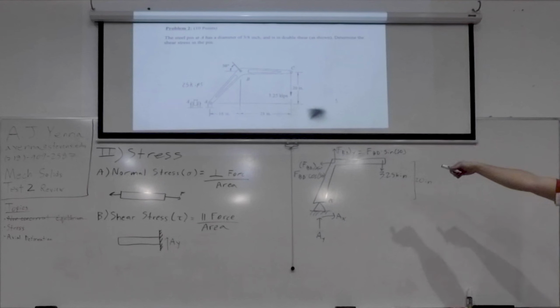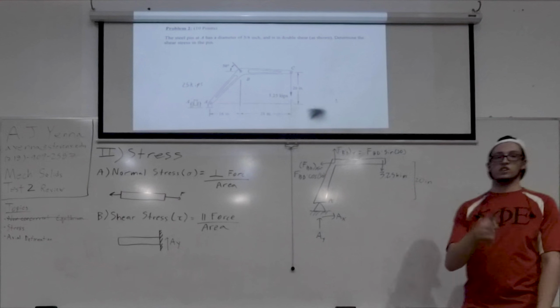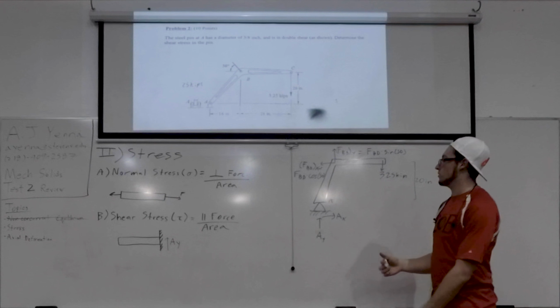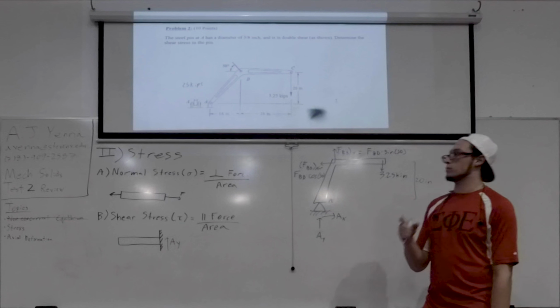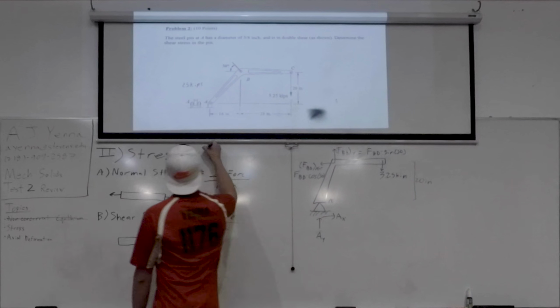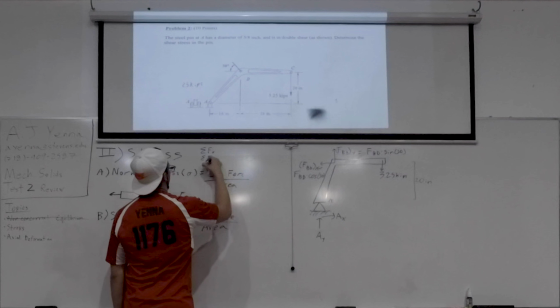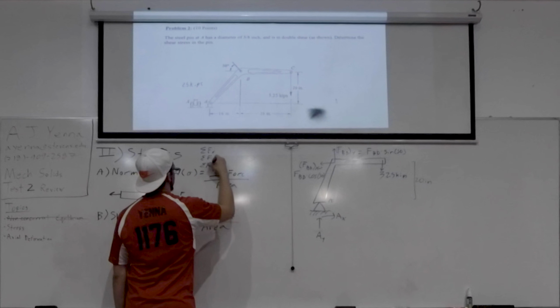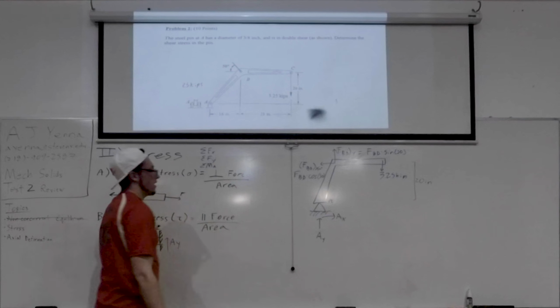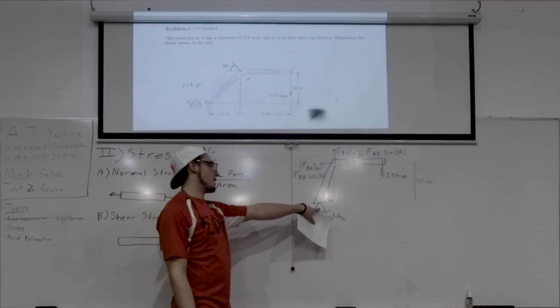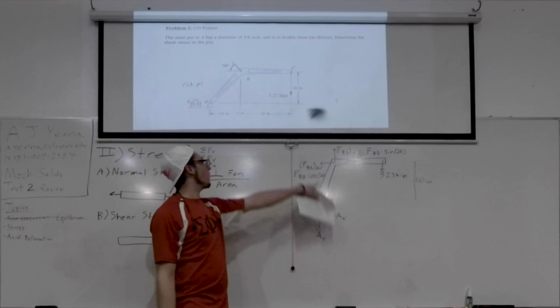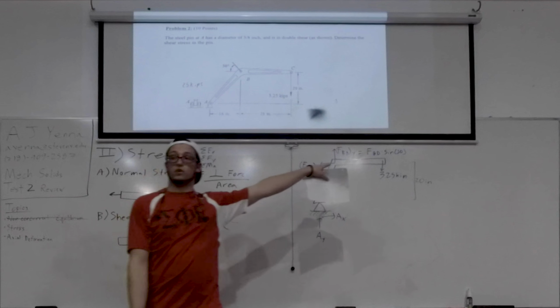Okay, so these are your forces now. So the exact same trick that I did in the first problem, the first calculation I'm going to do out of summation Fx, summation Fy, and summation of a moment through a point, is I'm going to take the moment through A because then both of these forces go away and we could solve for FBD in the first step.